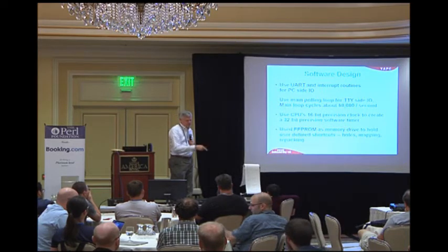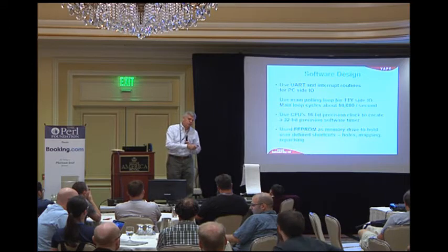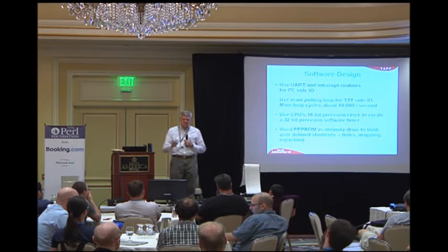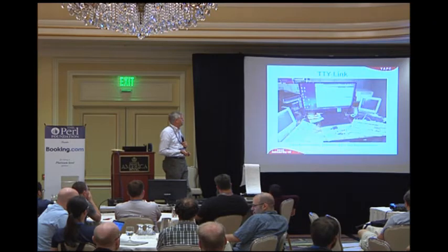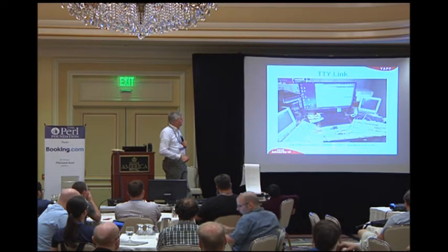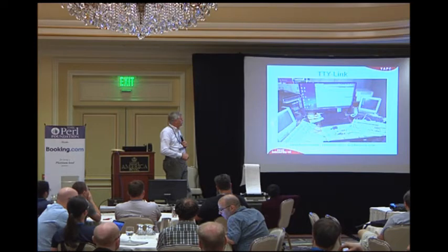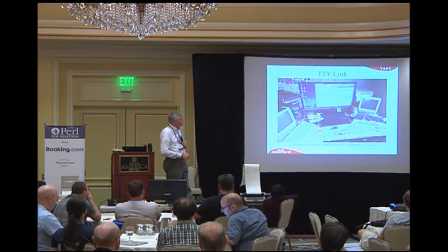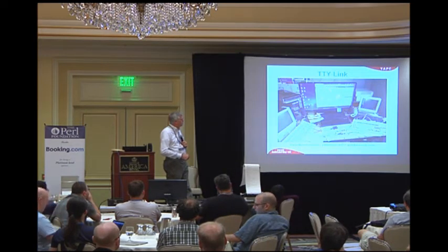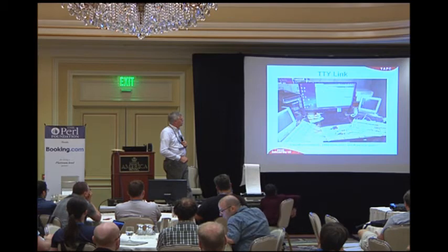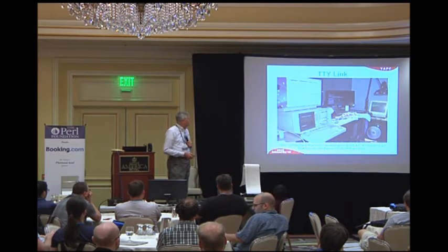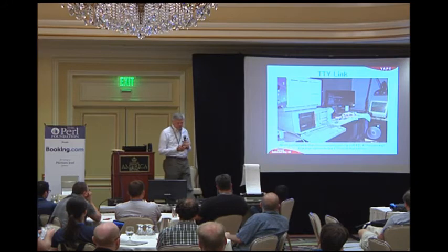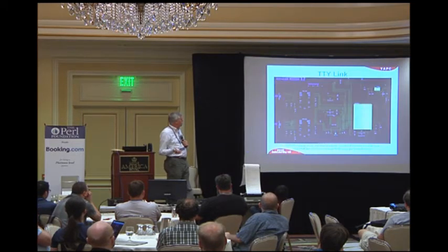So you can actually program on the teletype. When I hit W, I want the weather. When I hit N, I want the news. And it sends those commands to the Linux machine. So then I got everything working with my prototype. I have these terminals simulating the teletypes. It only takes about 2 seconds from when you press this download button here in the Atmel Studio to go through that programmer and reprogram that chip. It was a very fast, iterative process. I never got flow control working with the hardware, not sure why, but I ended up going with XON/XOFF, which is a software form of flow control.